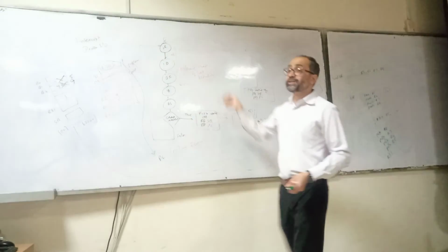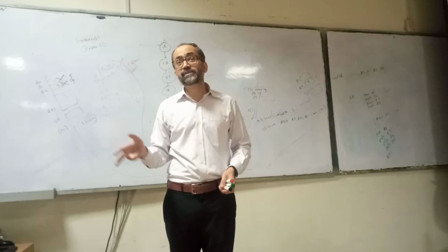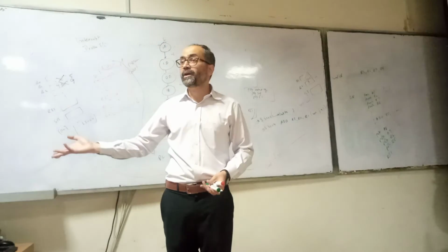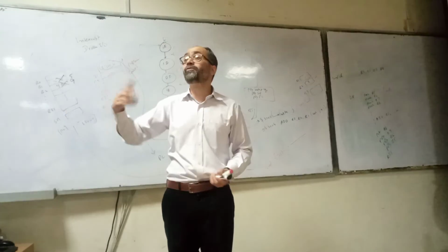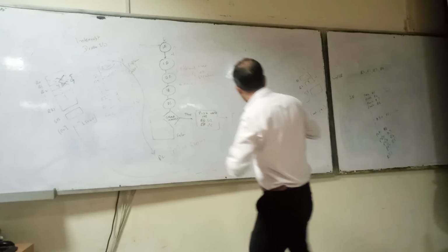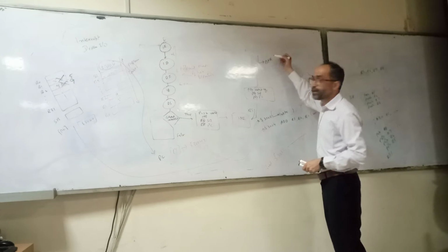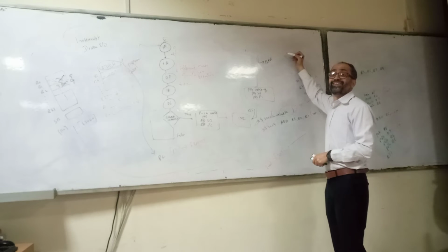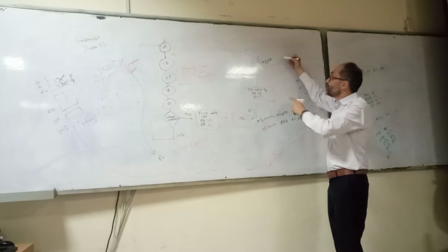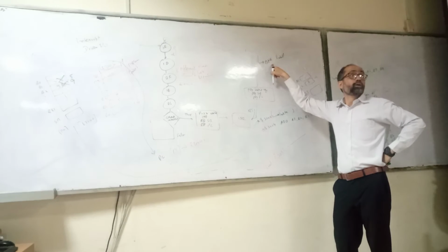Okay, now it can be a conditional jump instruction or unconditional. If it is unconditional, it is a jump instruction. If it is a conditional instruction, then what is the instruction? BEQ. Now, let's assume we have BEQ and the interrupt arrives here. First it will check the condition, and based on the condition, BEQ label, the condition can be either true or false.